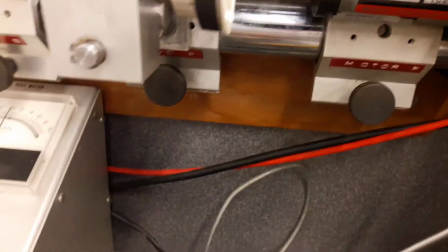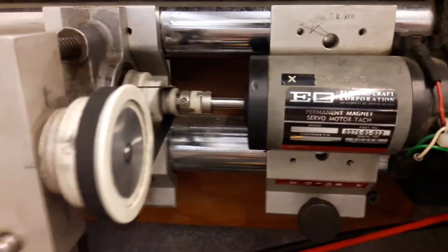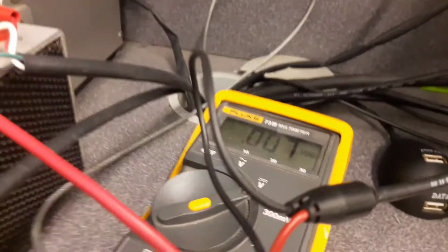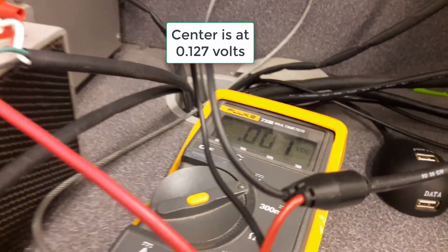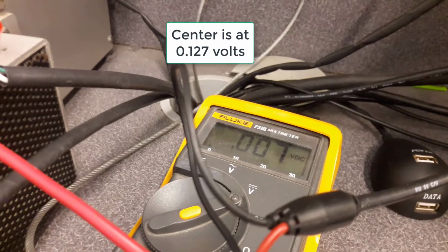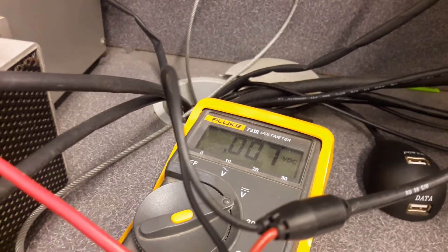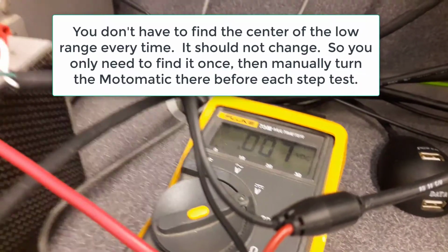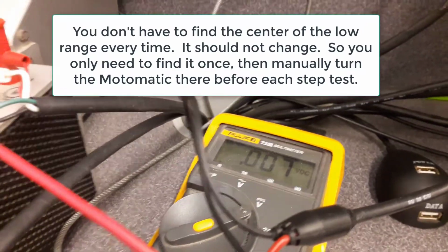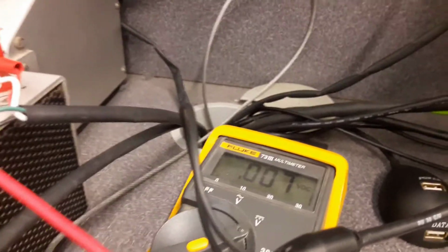And if I look up at this, I can't remember where the locations were. But anyway, what you should basically do is turn this until you get the center of those low values, and then you can start your experiment. You need to do that every time you do a step. Start off at the mid value of the lower stiction range. So I'll just demonstrate it again. Let's say that this is the mid value. When I do my run,